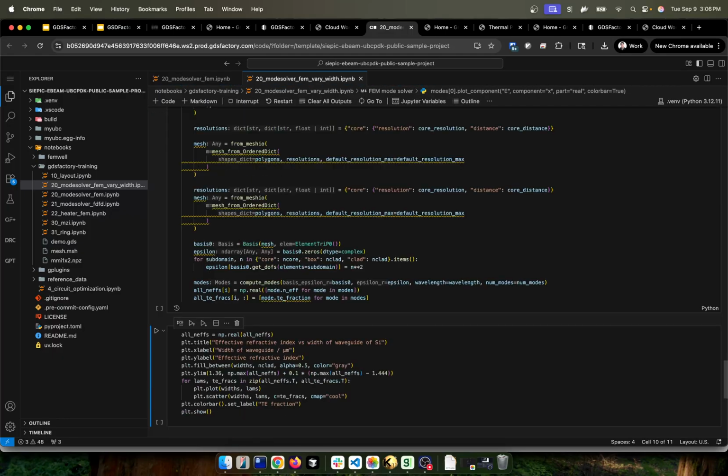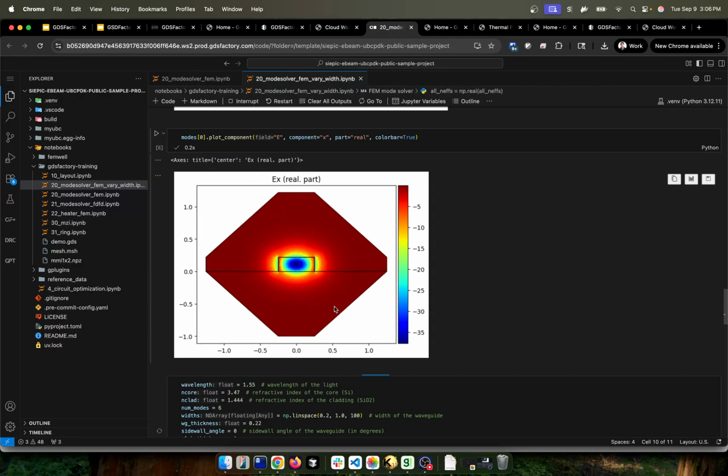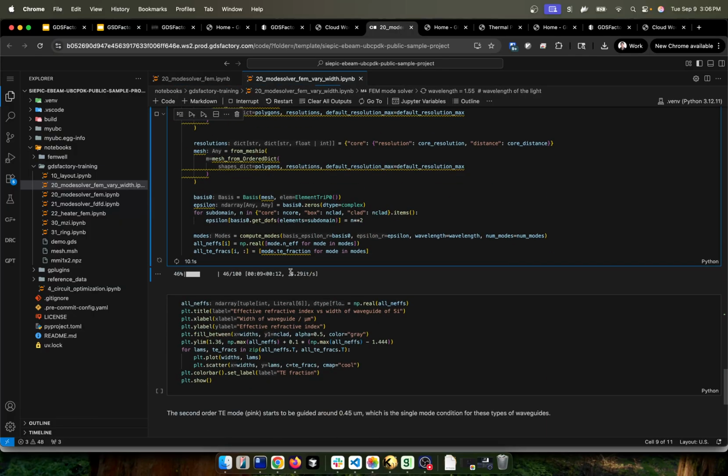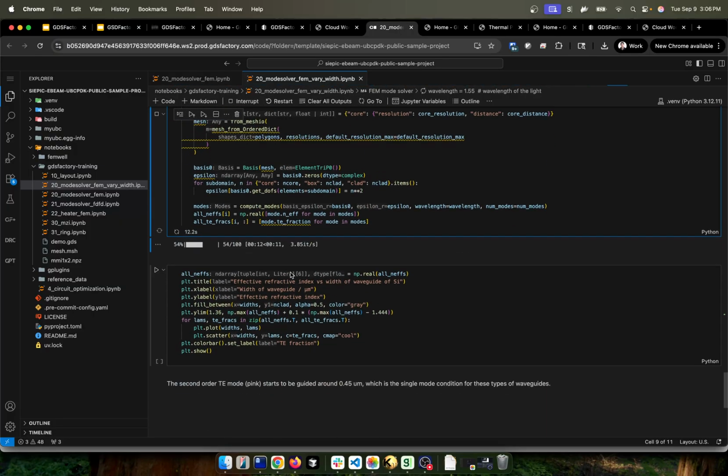When you do a silicon waveguide, the refractive index of the silicon material is 3.47. So this is more representative of the one you're going to be fabricating in the EDX course. And as I change the width of the waveguide, I will be supporting different modes. So in this case, once this reaches 100, I will be able to see the modes supported for silicon.